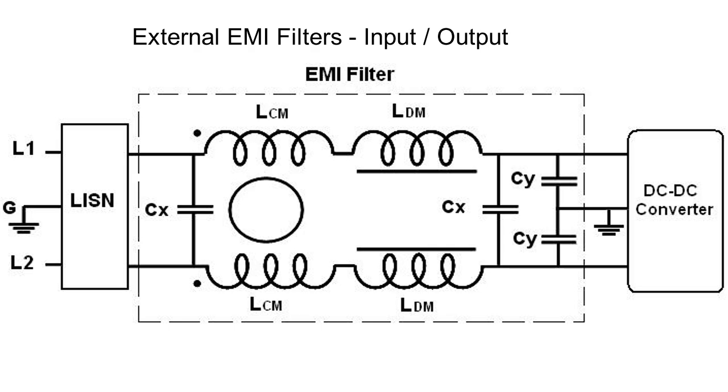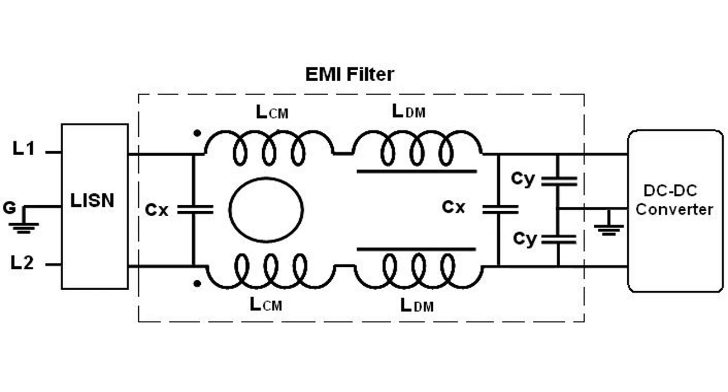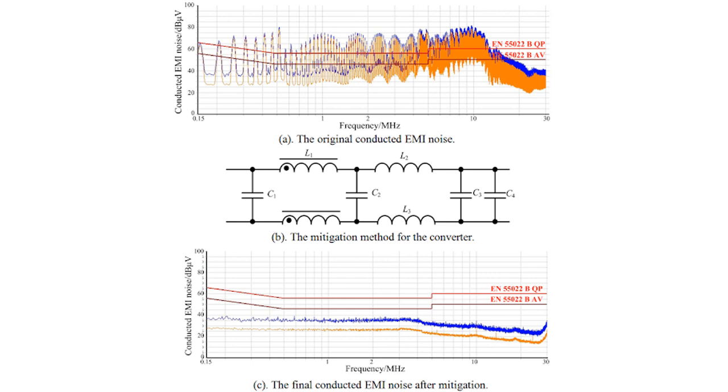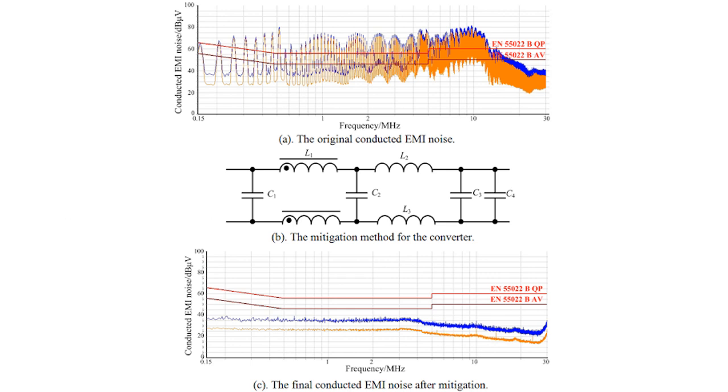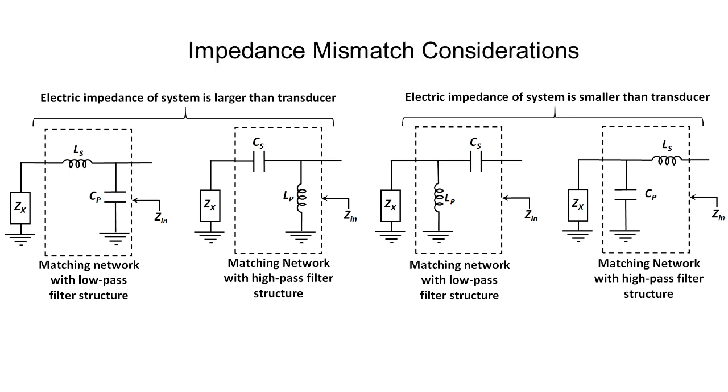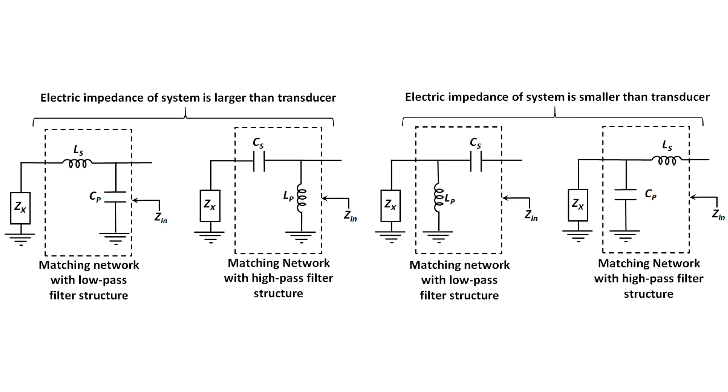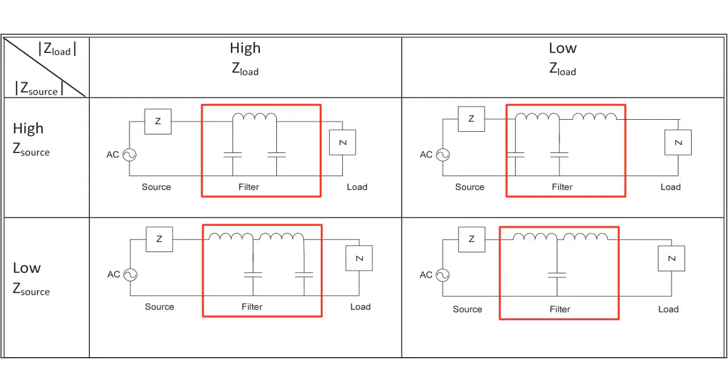If so, then great care must be taken to avoid undesirable effects by the stray inductance and/or capacitance of the filter, which may cause instability or performance degradation in the overall onboard power system. The designer must keep in mind the impedance mismatches between the input filter and power module. One way to prevent this is to ensure that the output impedance of the filter is much smaller than the input impedance of the power module at all frequencies.